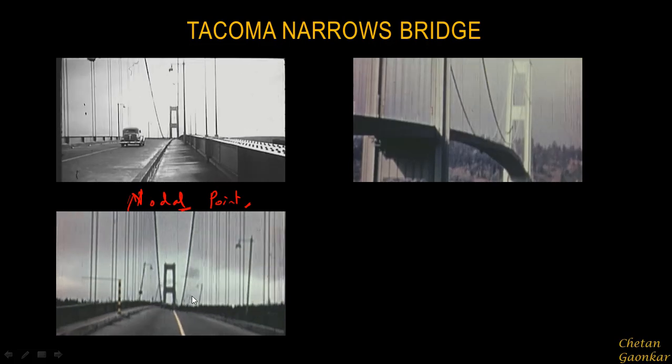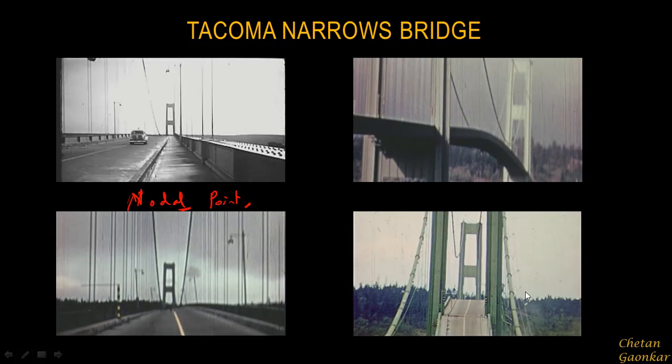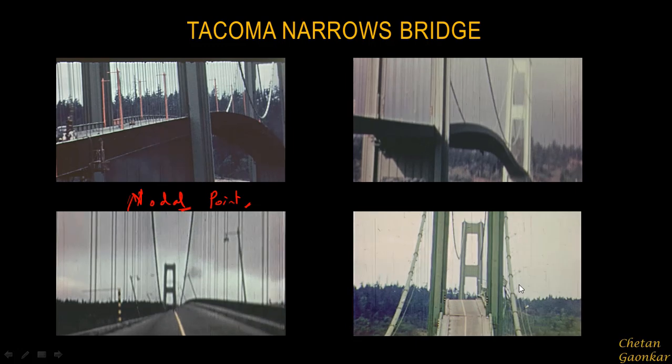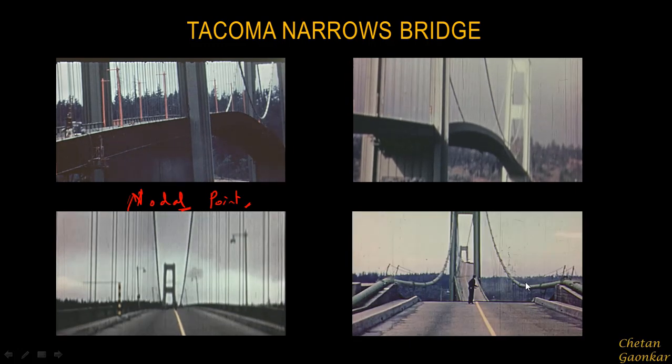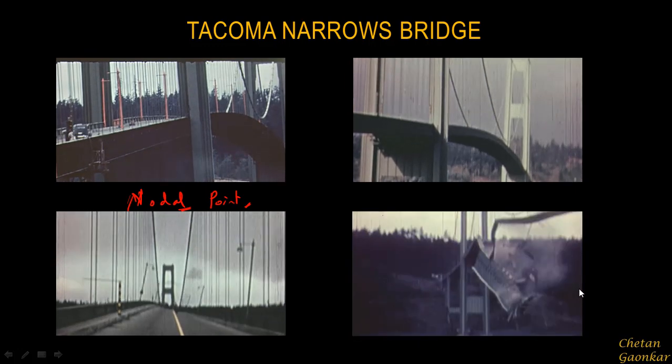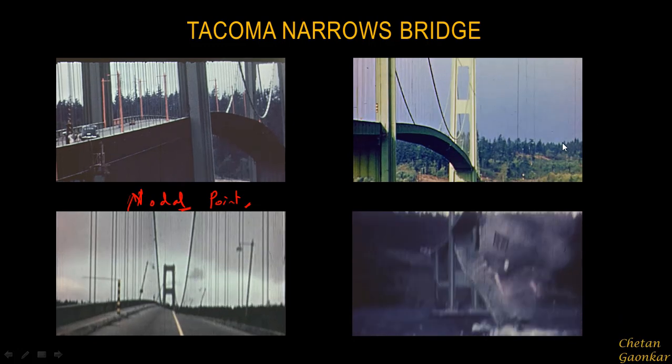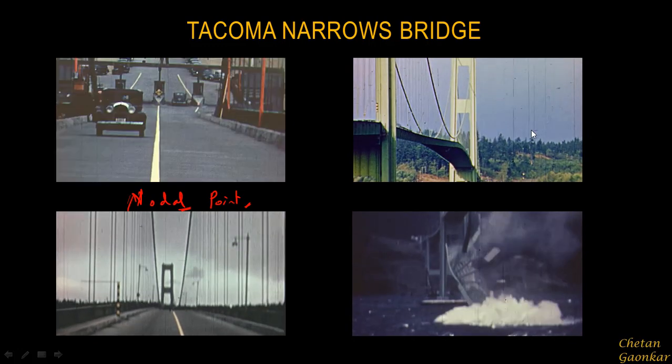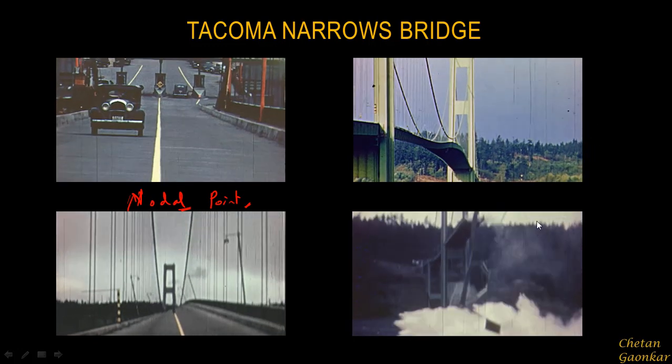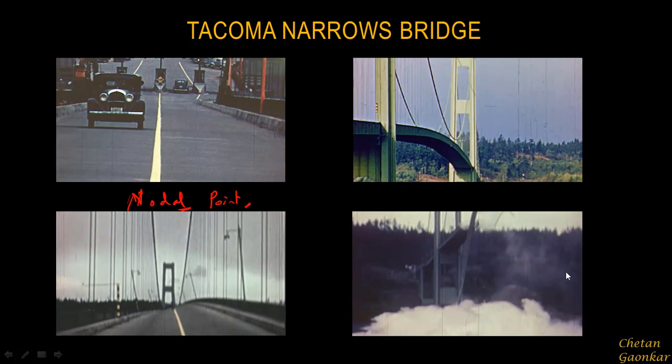And then in this last clip you will finally be able to observe the collapse of the bridge. It happened at around 11:10 a.m. So it had started experiencing this torsional mode at around 10 a.m., and within 1 hour this bridge totally collapsed.